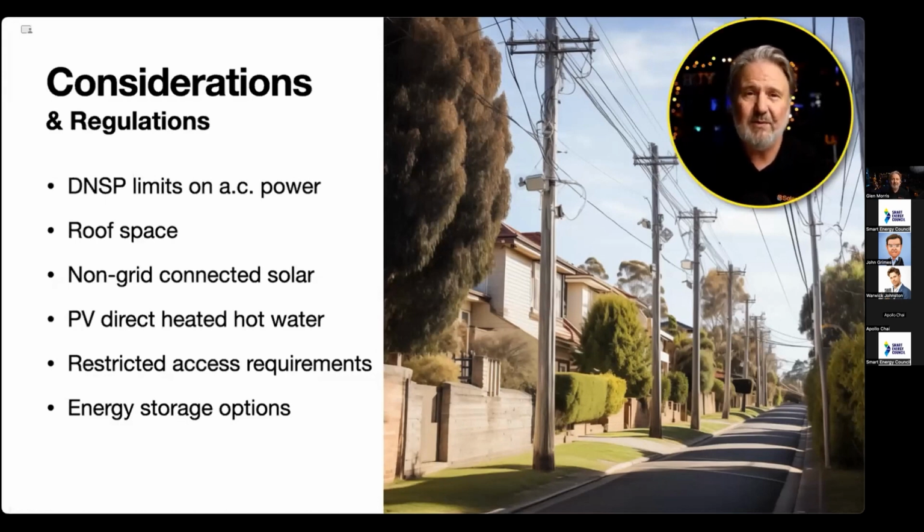That can often be a benefit, particularly if you've overpowered your inverter. Overpowering sounds wrong. It just means that you've got more peak PV power than the AC output of the inverter. But most hybrid inverters can also charge batteries while they're inverting at the same time. So they're sending 5 kilowatts into your battery and 5 kilowatts AC power out to your home. So energy storage can give you that extra boost. So there you go, a little summary of some of the options of where you can put solar panels.